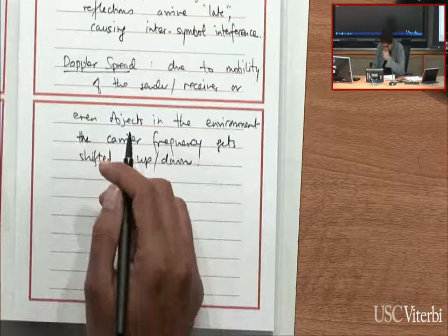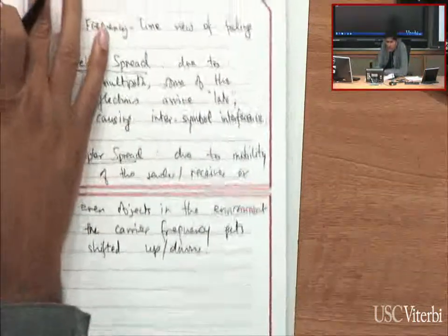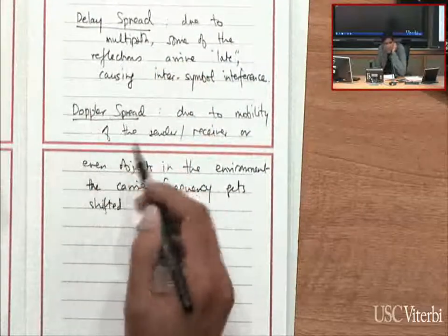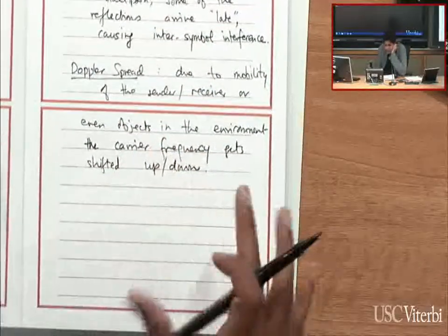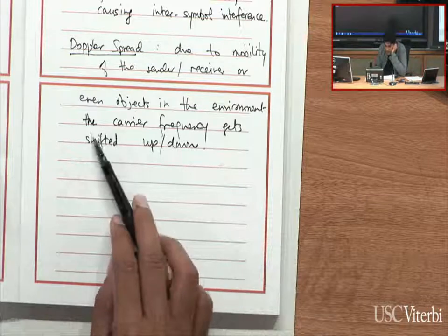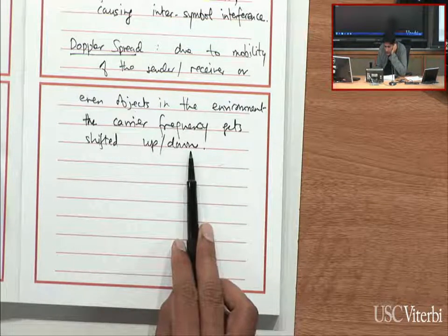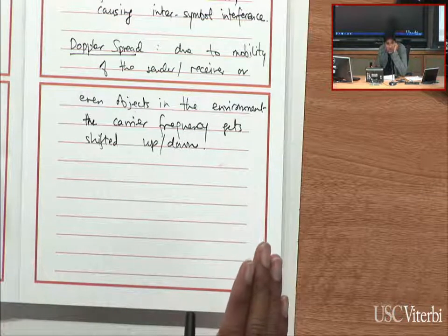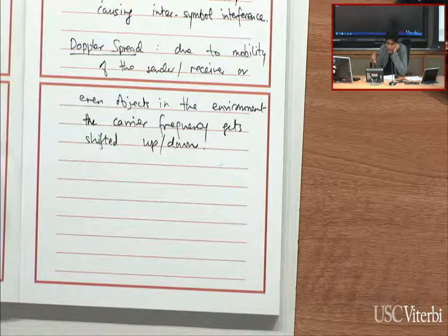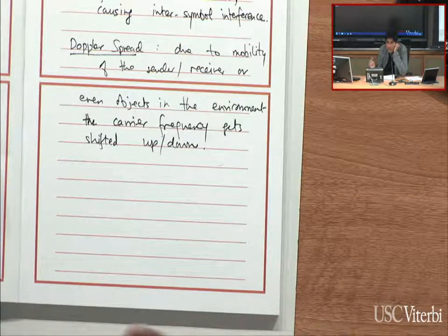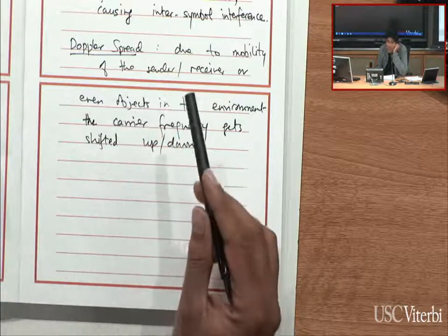Okay. So these two phenomena, one of them is kind of a temporal spread of the signal. The other one is like a frequency spread of the signal. And from a receiver's perspective, they can both cause problems. So on the Doppler spread front, what can happen is that because your carrier frequency is changing, you're going to start to see some distortions in your signal. And also, you'll find that as the carrier frequency changes, there are times when the signal looks really good and times when it looks really bad. This time-varying phenomena of the fading, how quickly it changes, is a function of the Doppler spread.